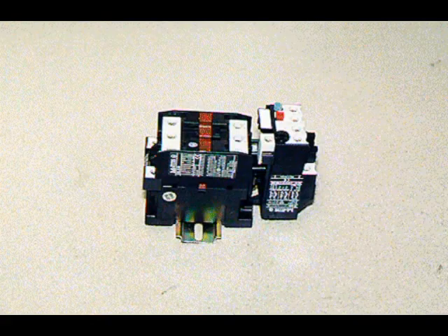If too much current is drawn during startup or at any other time, an overcurrent relay in the starting circuit will shut the motor down. There may also be a heat sensor in the motor that will shut down the motor if the windings overheat. Some large motors have vibration sensors and heat sensors to provide overheat protection to the motor bearings.